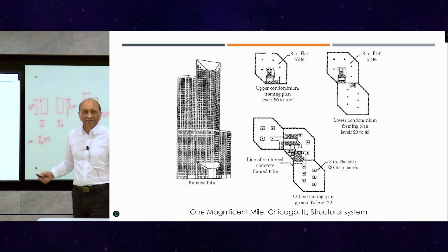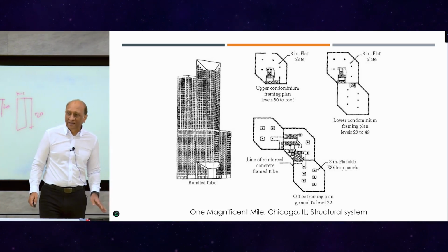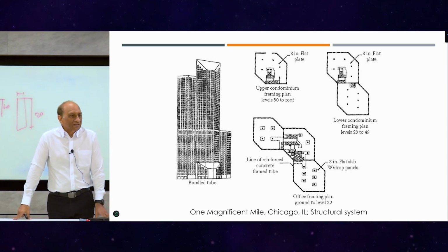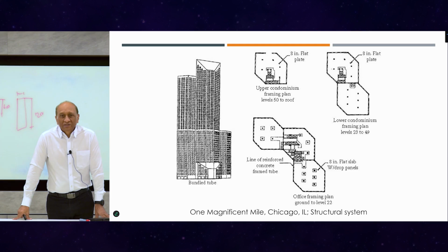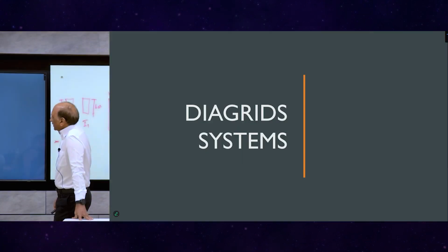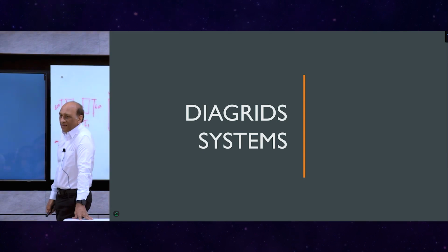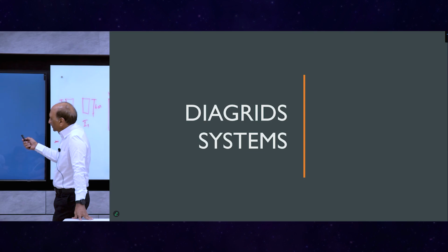The advantage of all this is that you don't need beams anymore inside. Things that architects just would like to have, no beams, right? And no outriggers, no belts, no nothing. That's the advantage of tubes, that they just convert the facade of the building into the structure. And that also brings us to the same system, very similar, replacing the tubes with the Diagrid.